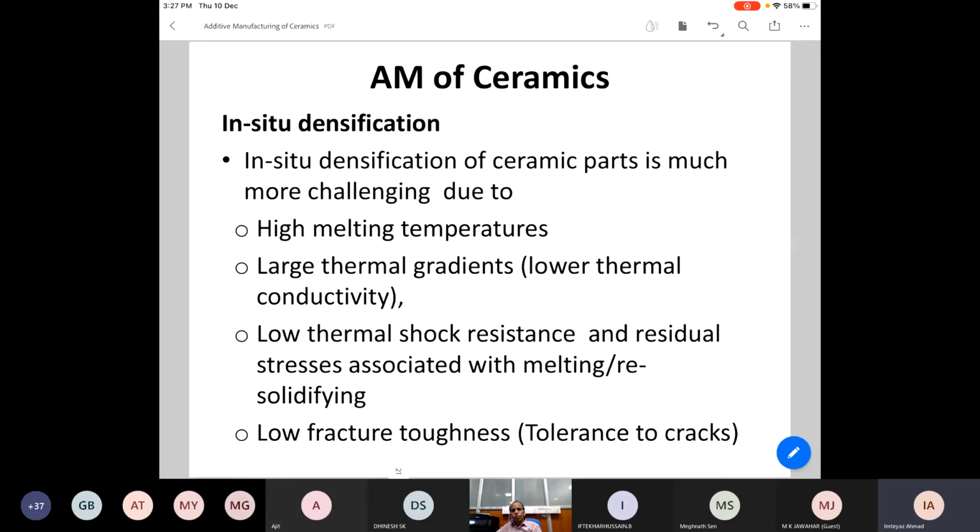And we have seen just now the TSR, thermal shock resistance, of ceramics is not good. So it will not withstand much, and it will eventually end up getting cracks. Once it has cracks, it becomes very fragile. Although ceramics are hard, in the presence of cracks, since the K1C or the fracture toughness of ceramic materials is low, it will be very difficult for it to sustain any loading, and it will break eventually. And so that's another problem.